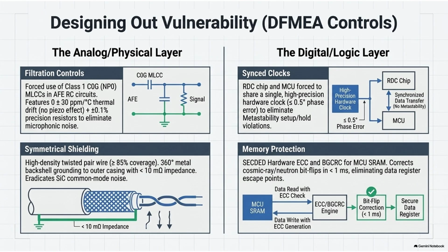Take the microscopic fretting wear we discussed earlier, the 5 micrometers of vibration rubbing the tin off the pins and exposing the copper to oxidation. The design solution is to lubricate the pins to block the oxygen. But how do you mistake-proof the application of grease inside a microscopic connector? Yeah, how? They utilize automated microgreasing combined with automated optical inspection, or AOI.